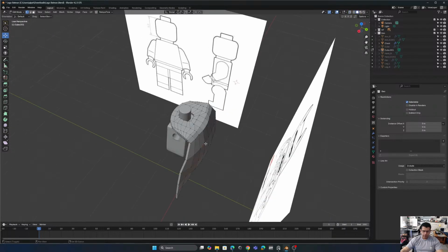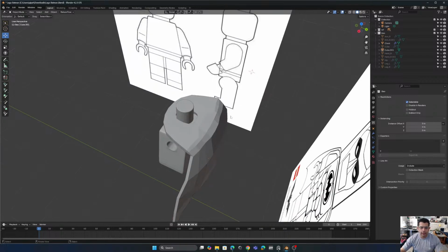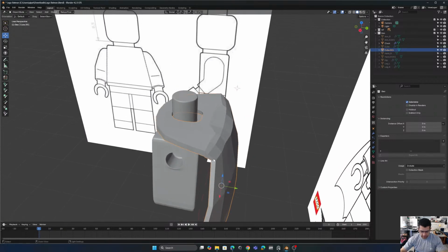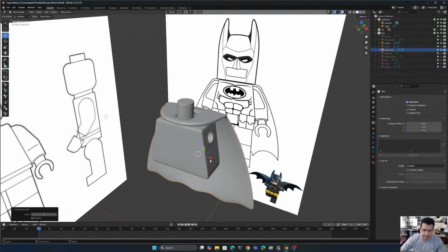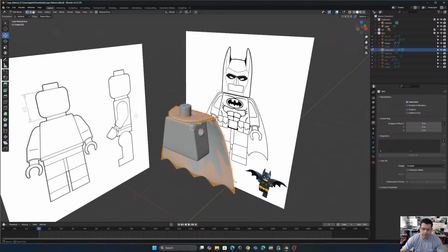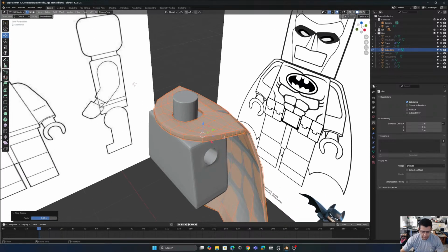Perfect. Now we're gonna get out of editing mode, Control 2, selecting this, and we're gonna smooth it a little bit. Now get back to editing mode, Shift Z to go to wireframe mode, select everything, Shift Z to go to material or shape mode, Shift E to have the chance to edit the smoothness. There you go, I think it's so much better.